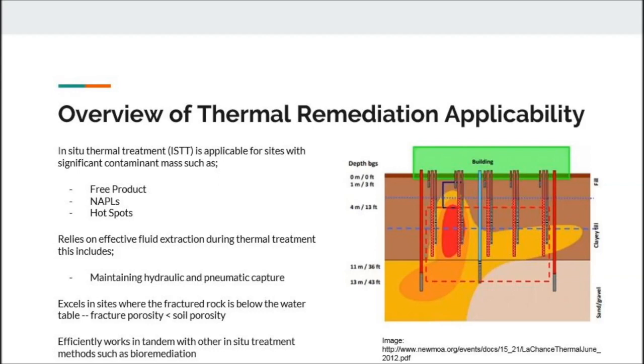Once the recovered fluid reaches the surface, traditional methods such as sedimentation, filtration, and adsorption processes that use granular activated carbon columns may be used. Carbon for the adsorption process can be regenerated on site with steam. Being able to regenerate your own carbon packing material on site will save many costs in terms of waste disposal.